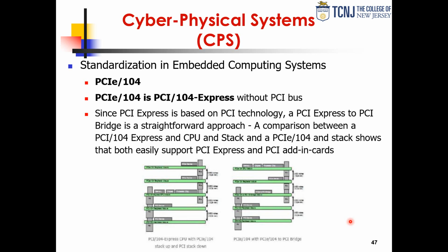and if you're still at this point, which should be a minority, if there are still any modules that are using PCI, well, it is simple enough to come up with a PCI to PCI Express bridge. So for example, if this is the PCI Express bus and this is PCI, you can have just a single board with both connectors, and that becomes a bridge.